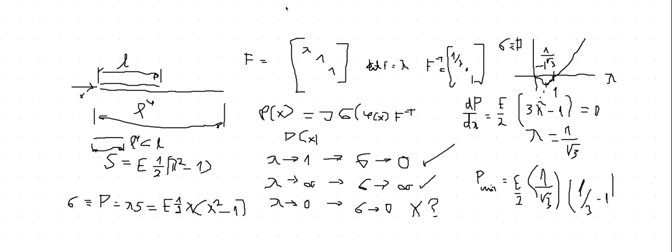So what's the conclusion? Well, Saint Venant-Kirchhoff material cannot be used for very large compressive strains. In fact, for all the strains that are below this value of 1 over square root of 3 for the stretch, you have a problem because you go into some kind of softening, which is completely unphysical without any plasticity or fracture failure. Nonetheless, this was the material which was very much used in many books on plates and shells.